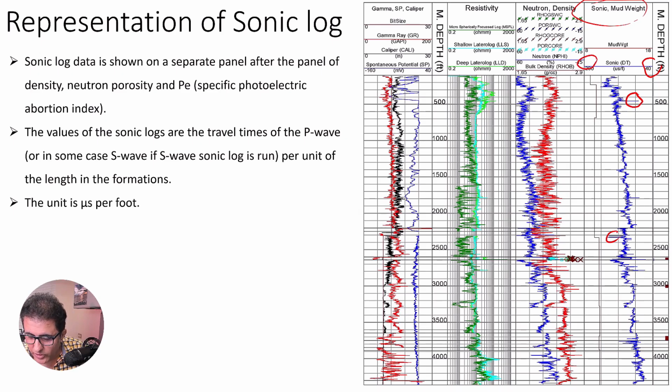And something that is interesting here, you see that the general trend of the seismic travel time is decreasing with depth. So what we can infer from this observation is that the seismic velocity increases with depth, and that's the reason we see lower travel time in deeper sediments. And it is something that is consistent with different experimental observations.